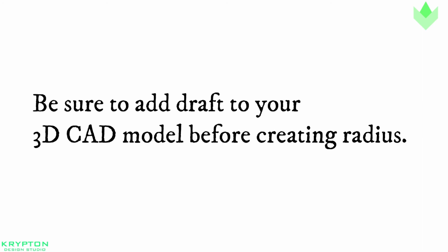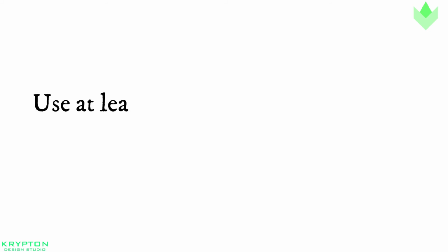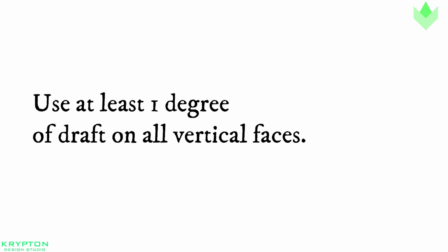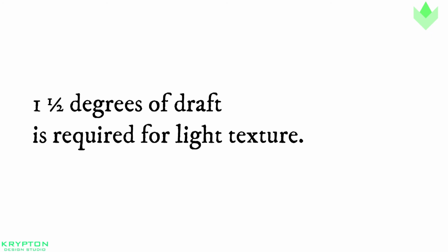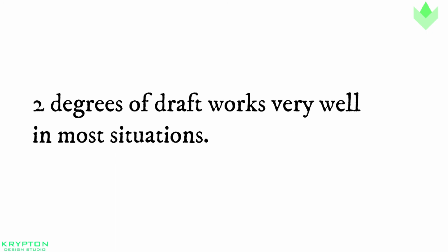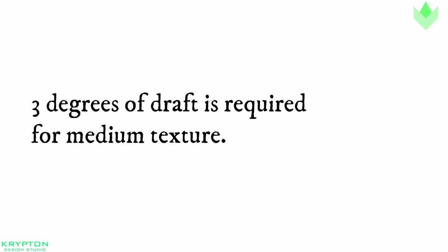Be sure to add draft to your 3D CAD model before creating radius. Use at least 1 degree of draft on all vertical faces. 1.5 degrees of draft is required for light textures. 2 degrees of draft works well in most situations. 3 degrees of draft is required for medium texture.